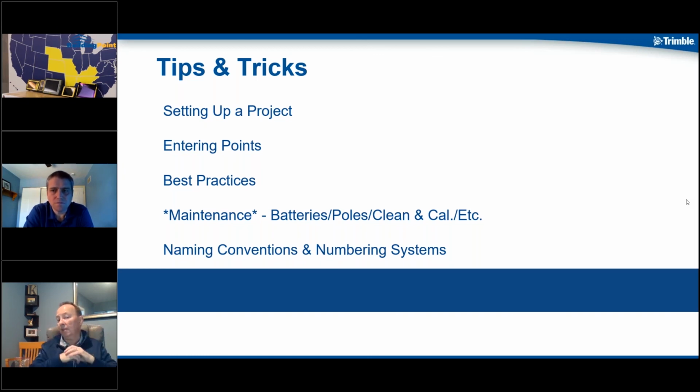Some of them will do it less frequently than that. That's at your discretion. That's a quick little field check, but we do recommend you get on the bench at least once a year, a lot of times once before every large project, so you've got confidence that instrument's running accurately, and you don't have to worry that that's the problem. If something else is showing up as an issue on the job site, we can rule that one out because we just had it calibrated, all right?